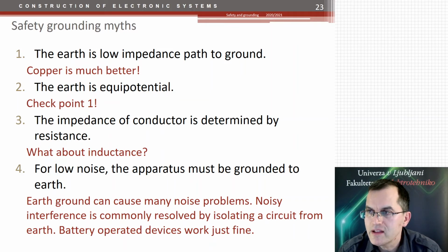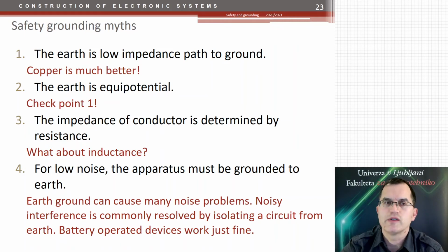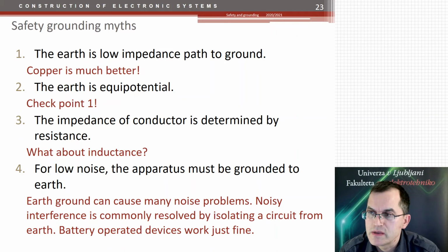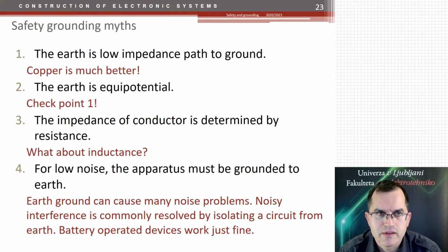And finally, if you follow all these myths, you would come to the conclusion that for low noise, every apparatus must be grounded to Earth, which actually is a very bad idea. The Earth ground causes a lot of noise problems.